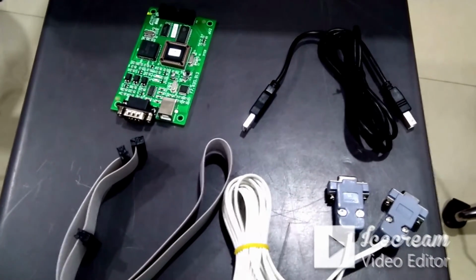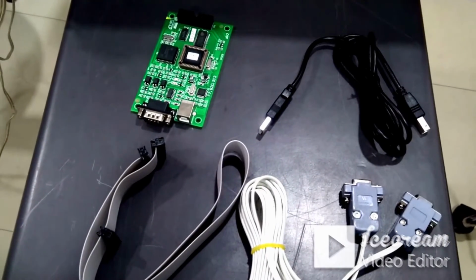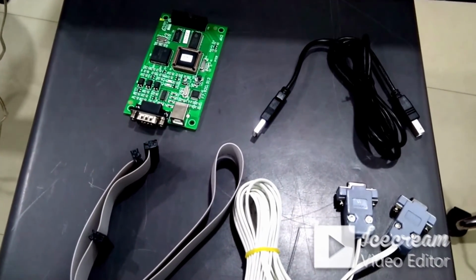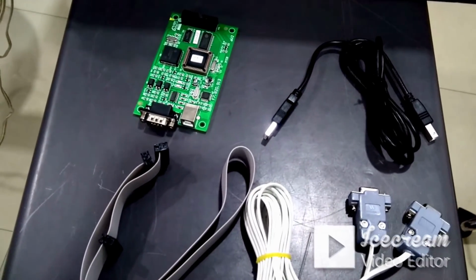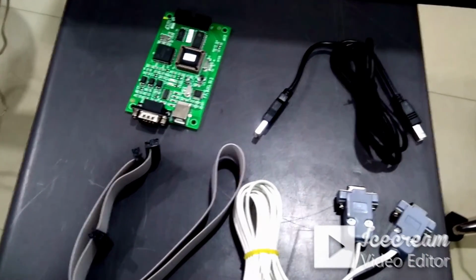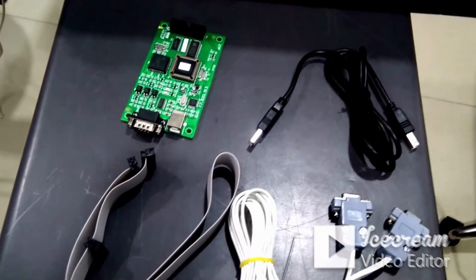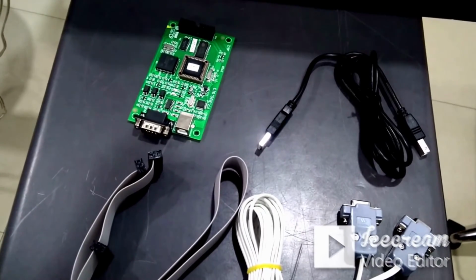One is on the hardware side, which is nothing but fixing the panel, connecting all the devices and fixing that loop cable on the panel and doing the Autolearn and ensuring all the field devices get registered or auto-learned by the panel. So that is the first part. And the second part of the commissioning is using the GST Define Tool.